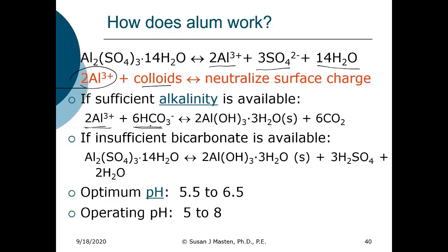And alkalinity in fresh waters is equal to my bicarbonate concentration plus 2 times my carbonate concentration plus my OH minus concentration minus H plus. And here your concentrations are in molar units.